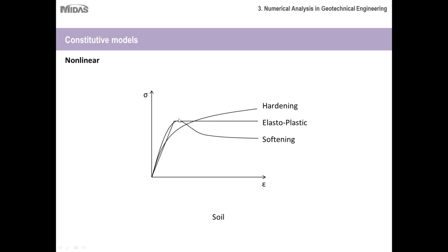Either the stress decreases, it loses strength, and it begins to taper off, or it'll harden and continue to increase its strength, but not in a linear way. It'll taper off as it increases. So this elastoplastic range is very critical to predict, where or when exactly you would reach this range, and to predict the strength of your soil afterwards.